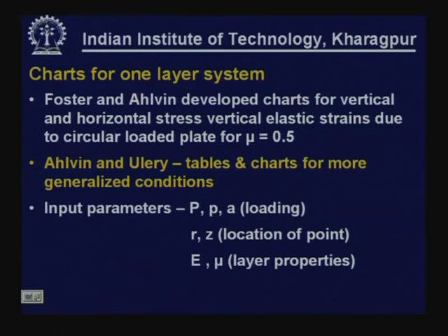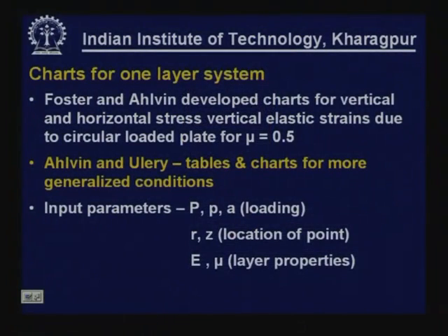So, what I am going to discuss over the next few slides will be some such charts that are available for solution of single layer system, two layer system and three layer system. In this slide we are going to talk about some charts and tables that are available for solution of single layer systems. The first set of such charts were developed by Foster and Ahlvin. They developed charts for vertical and horizontal stress and vertical elastic strains due to a circular loaded plate, for a Poisson ratio value of 0.5.